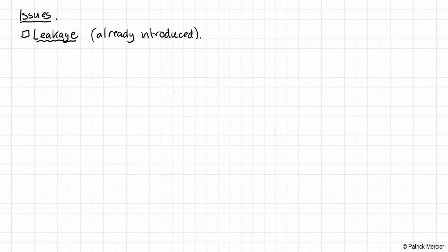All right, so this is happening from subthreshold leakage, diode leakage, and so on. Let's just say it's mostly from subthreshold leakage, but it could be gate leakage, diode leakage, and so on. Ultimately, what this does is it limits the minimum frequency of our circuit.